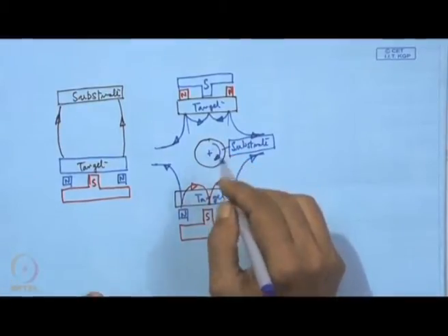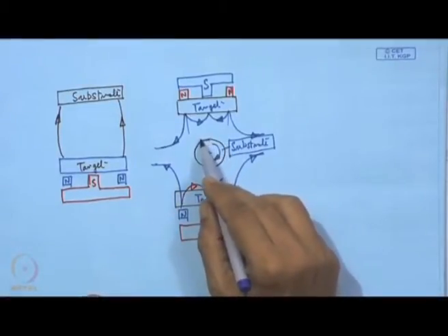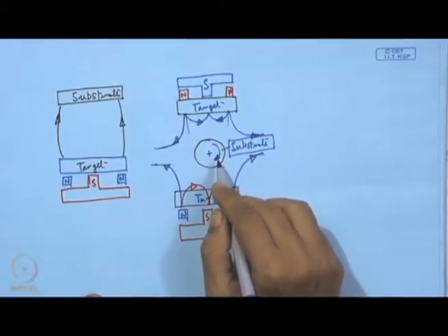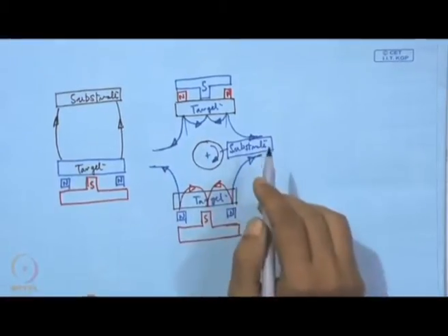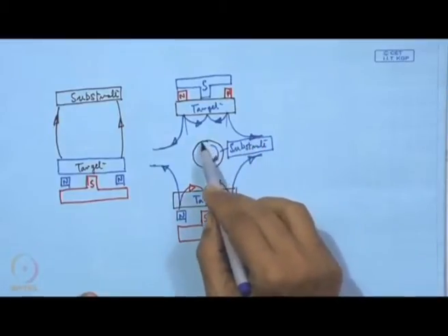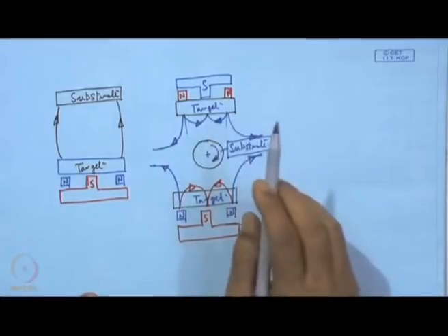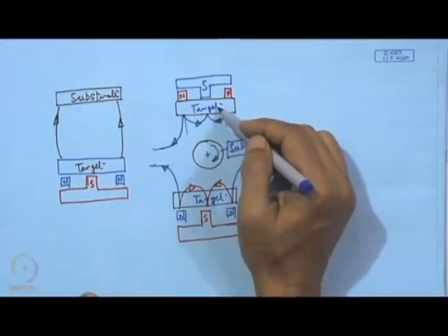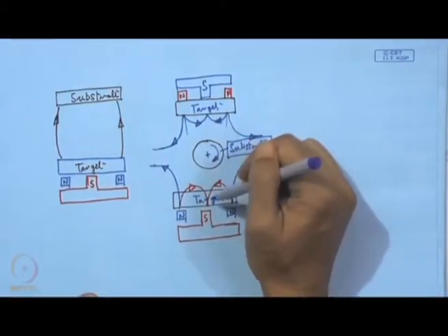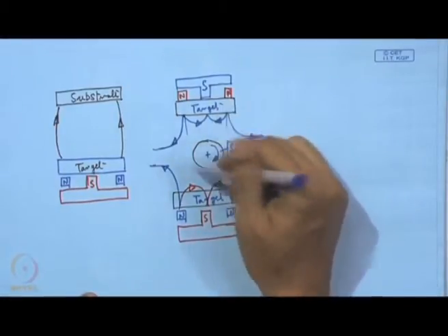So, we can also introduce some kind of porosity within the volume of the coating, and according to the need, if somewhere we need a porous structure for some reason and not a dense structure, that can be very easily obtained by this arrangement, by this option, where the north pole of one of the targets is facing the remaining part of this dual system.